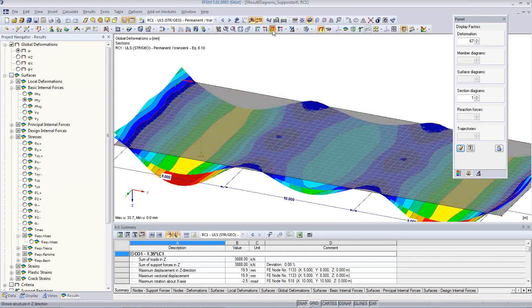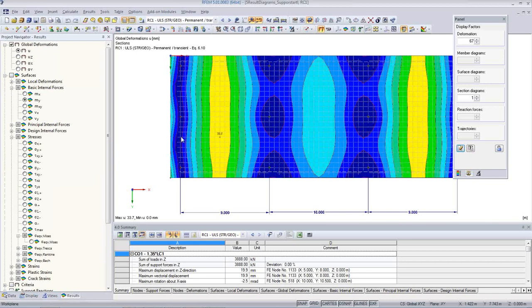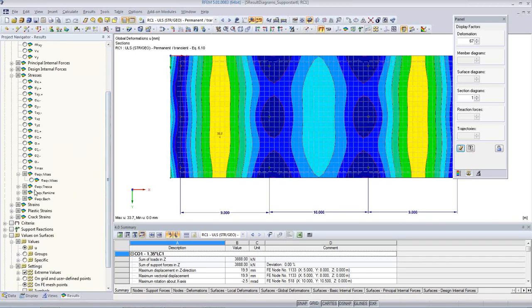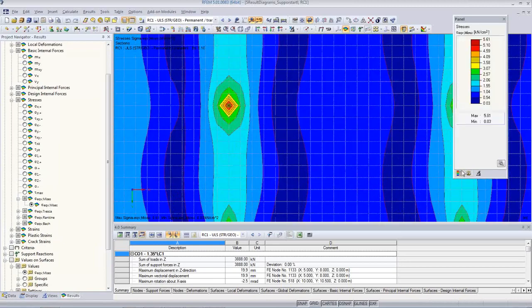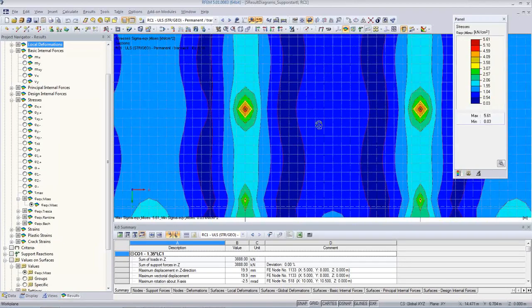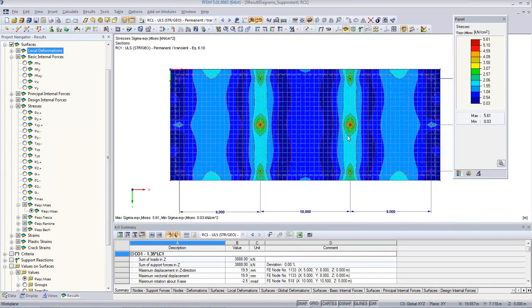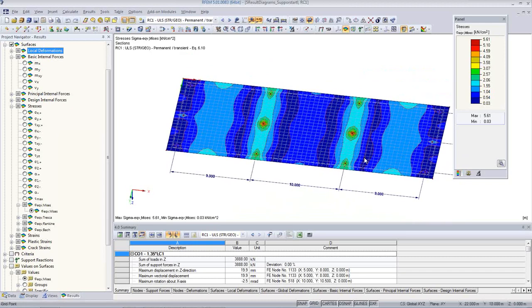What I like to point out is a typical problem, which are singularities. If I take a look at maybe the equivalent stress or forces, then you see here high concentrations of stresses actually on those points. So first of all, how to find singular points, how to find problematic points. Typically it's locations where there are high stress gradients. If you make the mesh dense, you will get an infinitely high value, and it's very steep. You will have a very steep angle in the change from one finite element to the other one.